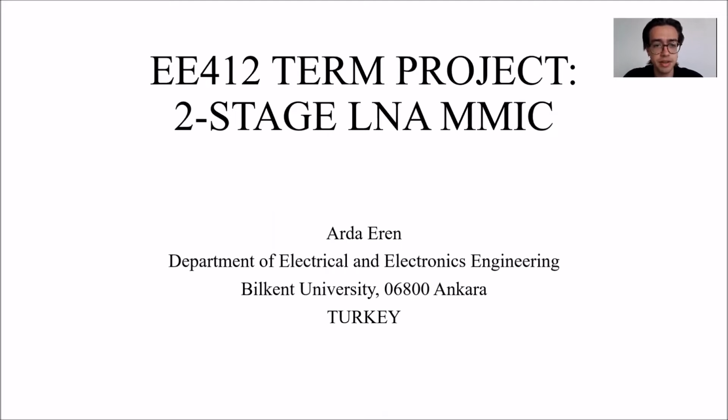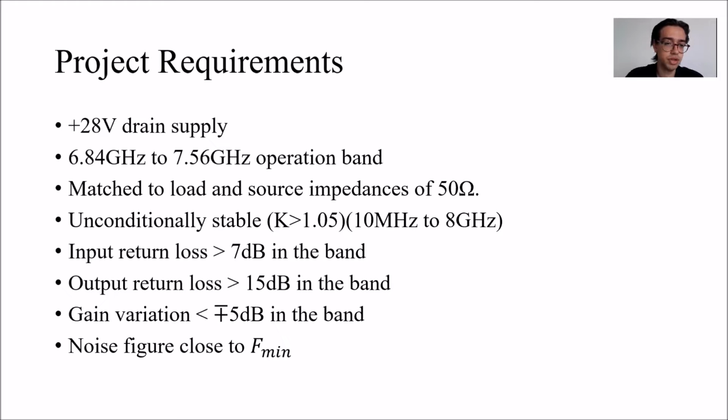So here I'm going to present my term project for EE412, which is a two-stage LNA MMIC design. The project requires a 28-volt drain supply available to both stages, and this MMIC has an operation band of 6.84 gigahertz to 7.56 gigahertz, with matched load and source impedances of 50 ohms.